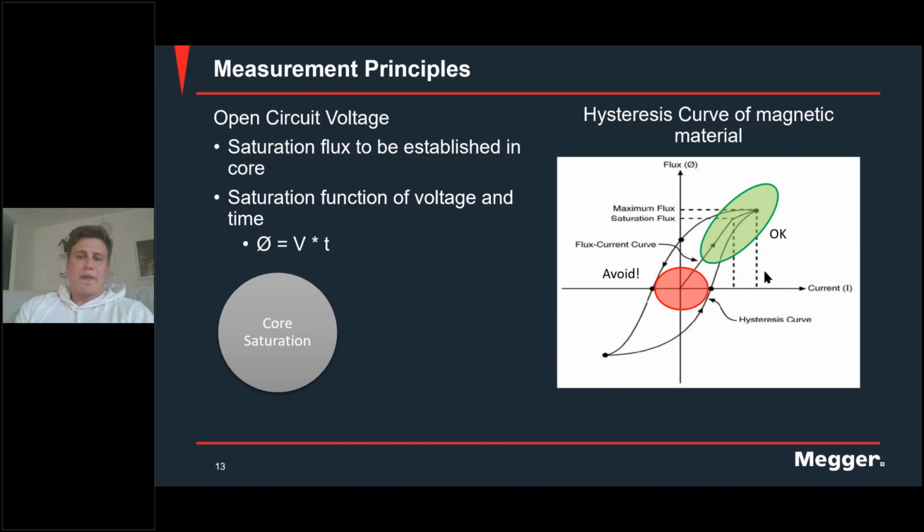So the difference, or how it affects how magnetized the core is, then how much inductance we have left, and that might affect the time constant to get a stable reading. So for example, 100 ampere will magnetize the core more, and then you will have a lower inductance, resulting in a faster stabilization time.